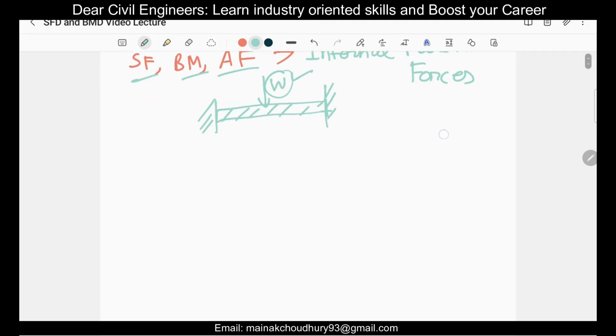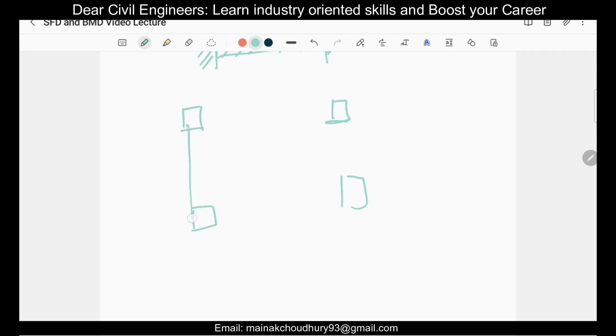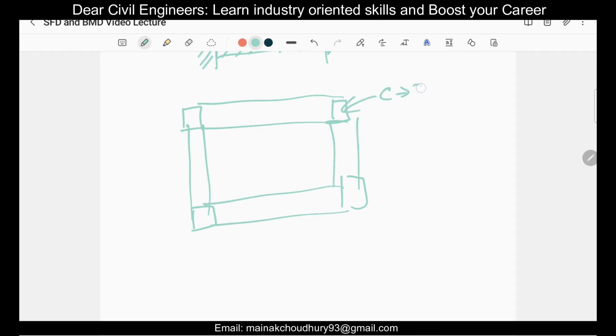In terms of designing a structure, whether manually or with ETABS or Tekla, first of all we define the sizes of the members. We make the beam column plan and take the sizes, suppose the column size as 300 into 300 and the beam size as 300 into 350.